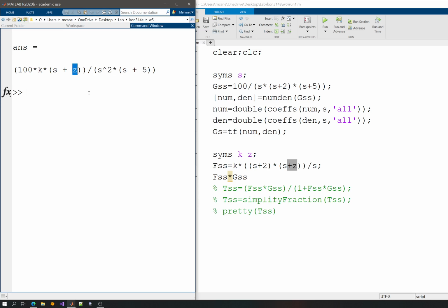But you can maybe make a sketch of your root locus using pen and paper and try to calculate where the zeta should be for your desired point and the angle condition. You can go ahead and choose the z such that my angle condition will be satisfied at the desired point. That is an alternative way of solving things. I'm going to show you the algebraic approach here.